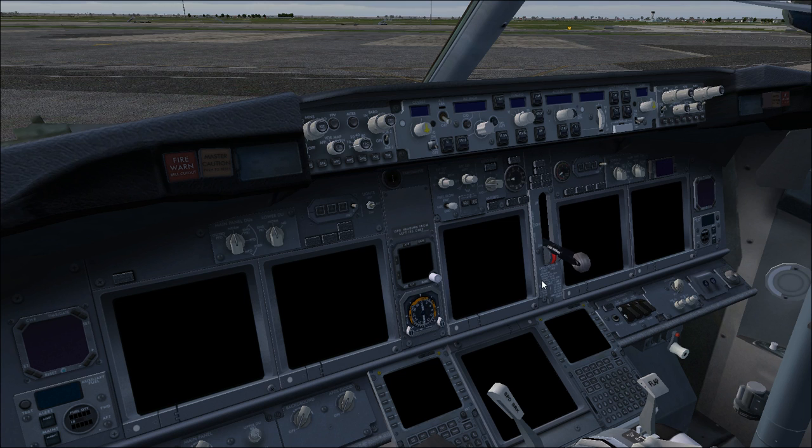Those 2 units can talk to each other. There is a way to select only one of those 2 units to print the data on the screens in case one of the 2 is faulty. They take information from a bigger system that I will talk about later, and they only calculate and present the data on the screens. As said, we have 2 of them, and they are controlled by different switches in the cockpit that we will see later.